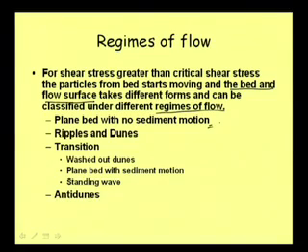So, first of course, as we know, it is a plain bed with no sediment motion, just as rigid. Then when it starts moving, it forms ripples on the bed of the river. Maybe many of us, when traveling in a river, find some sand deposition, and we will find some small undulations in the bed, and that sort of undulation we call a ripple.